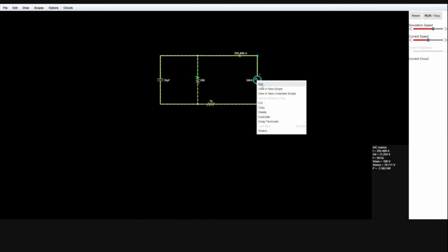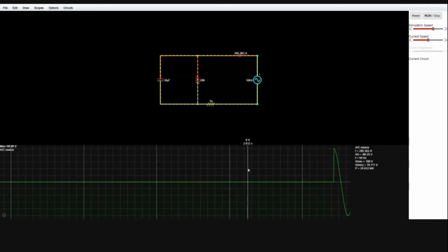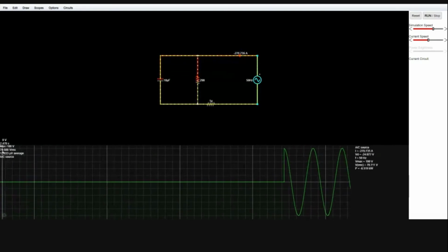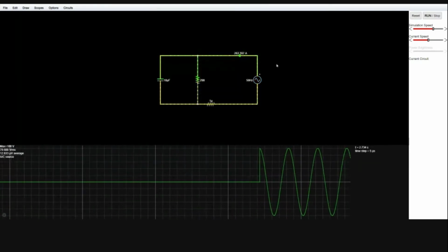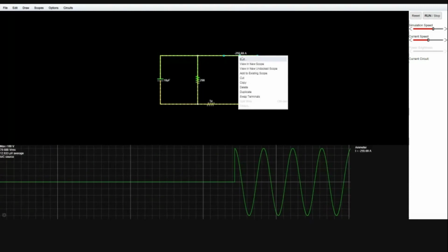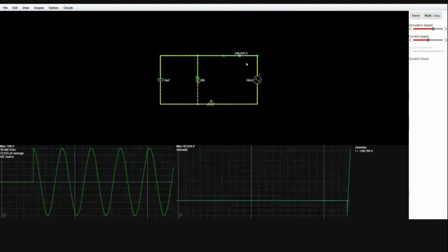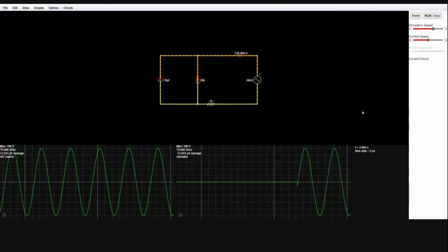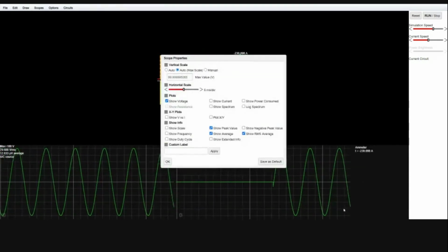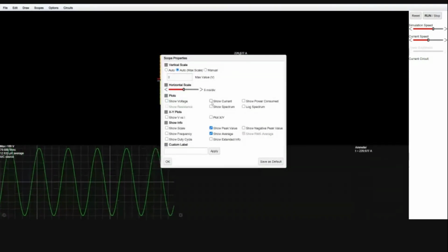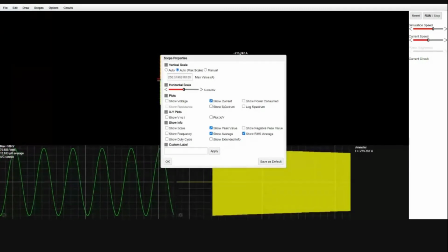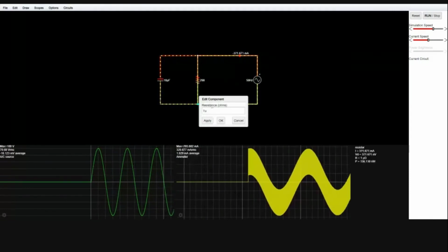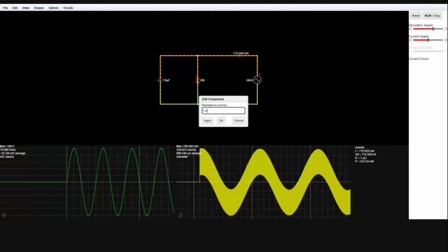So now what do I need? I need the magnitude of V test, which is something like this. And I need I test, the current value of I test, right? So when I view this, essentially this is just showing me voltage across the ammeter. This is wrong. I need to go into settings, remove show voltage and enable show current. Okay, this value will not work. Maybe this value is too small. Let me use 1 milliohm.